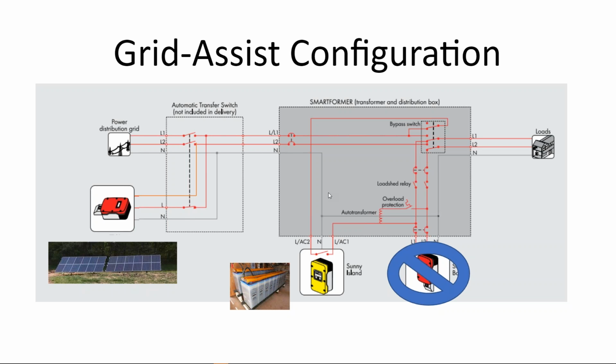Now, this is a different kind of system called Grid Assist. And I thought I'd mention it because it does have some commercial applications. I use Grid Assist in residential battery systems when we're facing punitive interconnection charges. So in my region, if you interconnect a solar array to the grid, not only do they only pay avoided cost for the outflow, but they'll also increase your fixed fees.